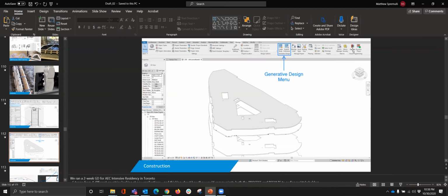I have a question about generative design as well. In Grasshopper, we have Galapagos, and we have two types of solver, the evolutionary solver and the simulated annealing solver. Sometimes the evolutionary solver doesn't work well, and the other solver, simulated annealing, works better because each parameter doesn't have a relation.